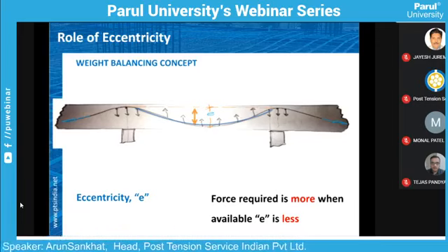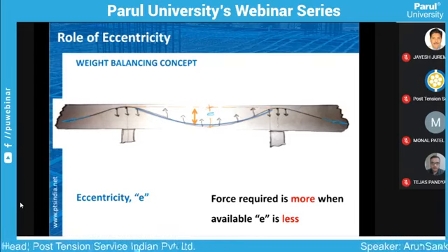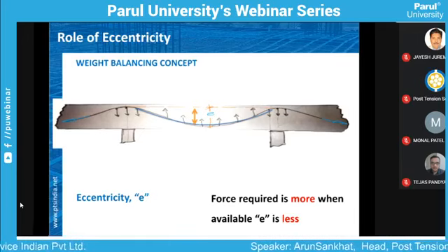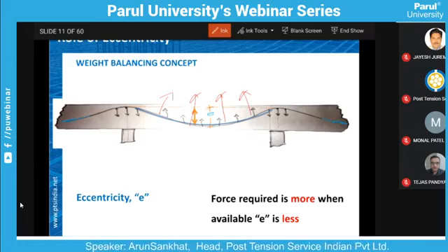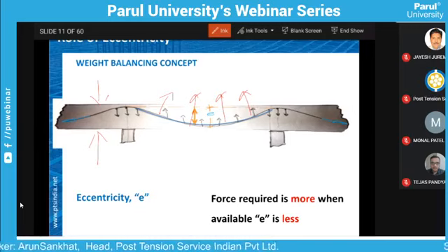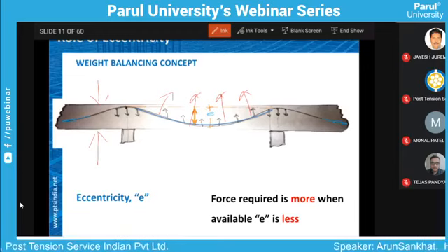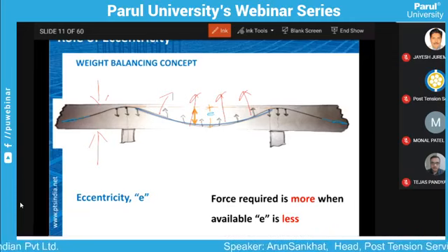The PT has to be there, and the PT does its role very well, actually. So here what happens is we can have this upward thrust, and with the help of this upward thrust we can minimize the actions of the downward force, and because of that we are able to minimize the depth of the member ultimately. So this is one of the advantages of having post tensioning or pre-stressing. The other advantage is related to its durability, or crack control. We'll see in the slides.